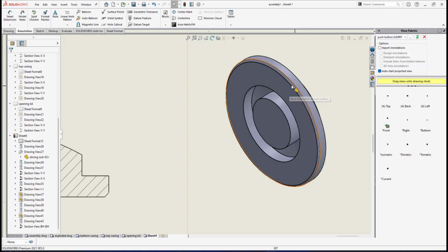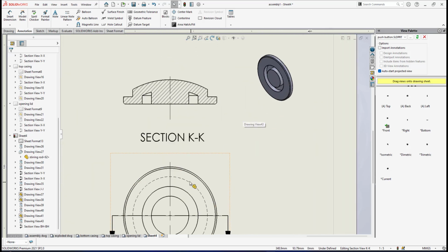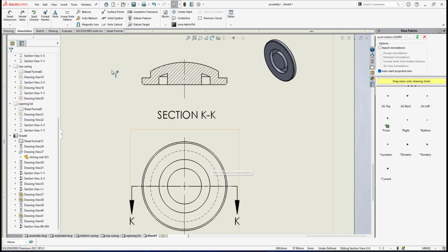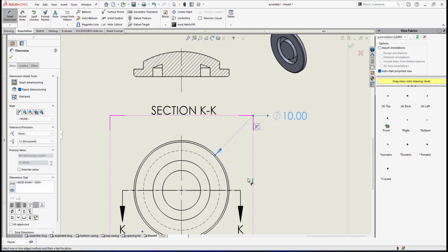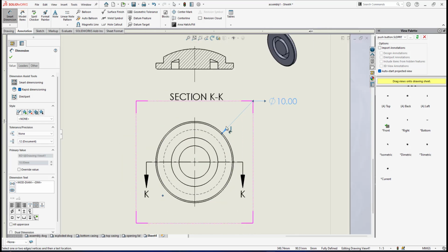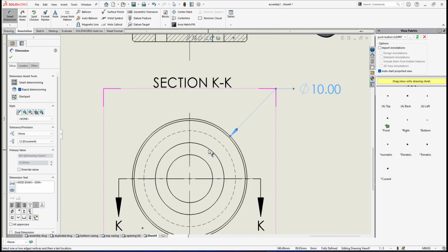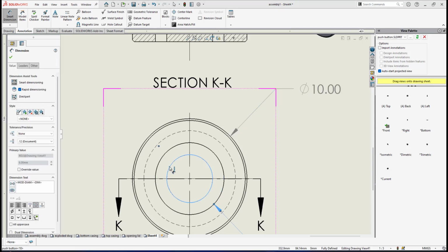Actually, I have kind of a chamfer here, and that's why I have a double line chamfer. Alright, the first thing to do is the diameter here, 10, and also whatever I can see in this front view, the outline, for example, this inner diameter here and also the diameter of this protruding cylinder. So that I will show you, since this is a solid line, one is here, another one is this one.